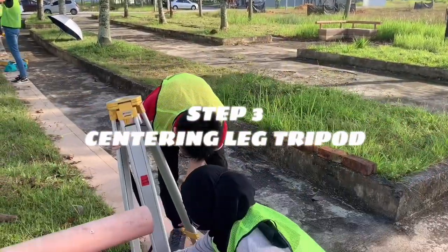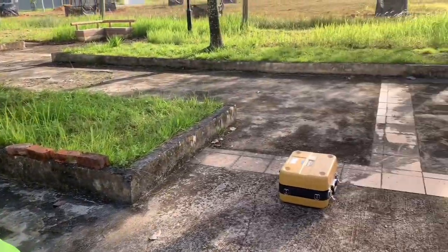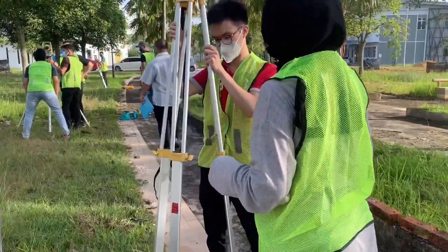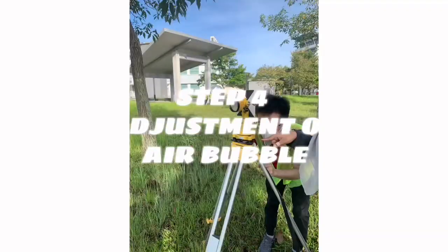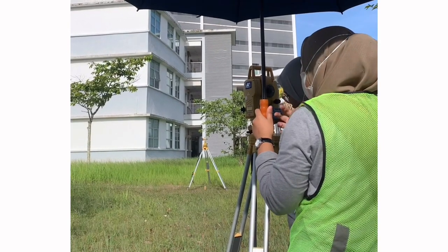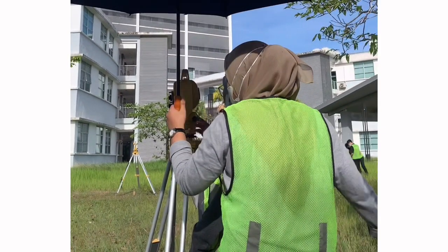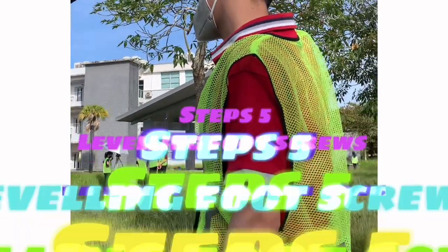Step 3. Centering the tripod legs. Centering is carried out by loosening the screw, tightening the tripod, and moving the tripod until the optical plummet eyepiece displays just above the point. Step 4. Adjustment of the air bubble. Perform adjustment of the air bubble. This adjustment is supposed to place the air bubble inside the center of the tube in any direction shown through the binoculars.